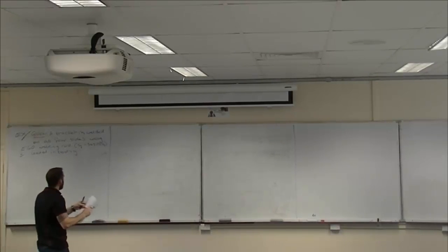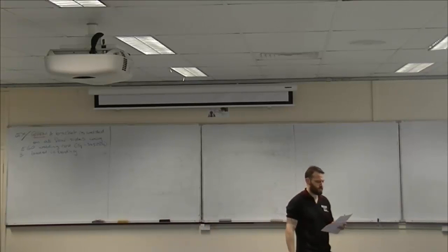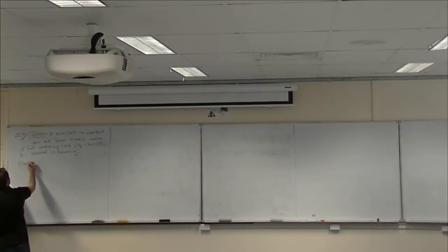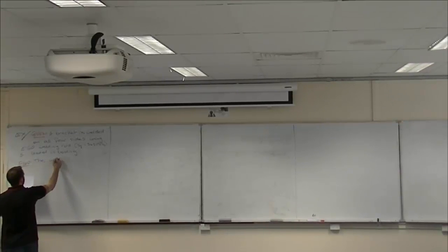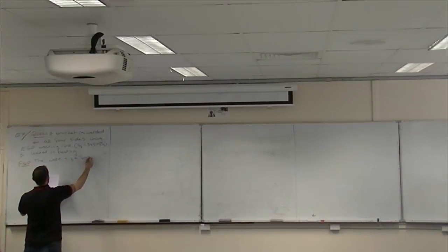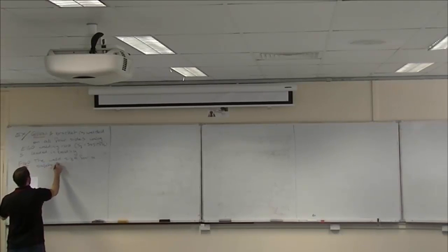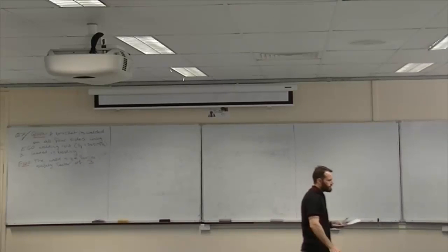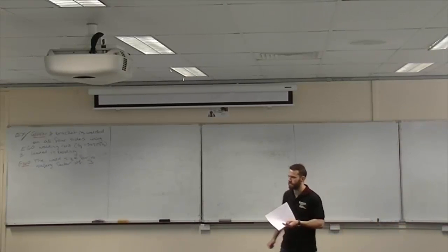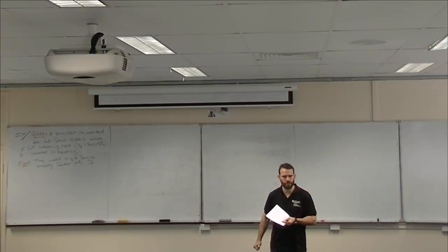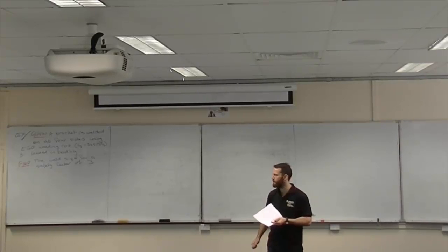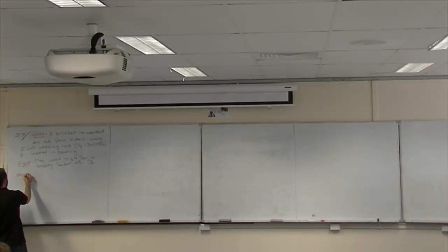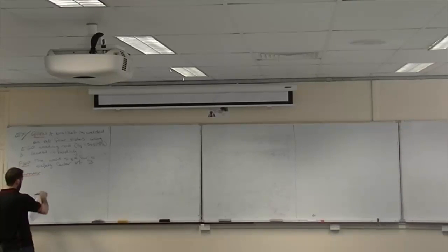So we have some rectangular weld group. We've got E60 welding rods, which in this case we're going to use SY equals 345 for the specific welding rod that we're using. We're finding the weld size for a factor of safety of 3. We tend to use a factor of safety of 3 quite a bit with welds because of the unknown factors around how good the actual weld process was, whether there were bubbles and crap left in it, or whether it was a really good welding process. But it's really just case specific. Let's do a bit of a schematic.